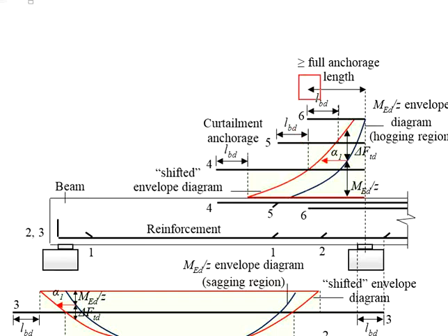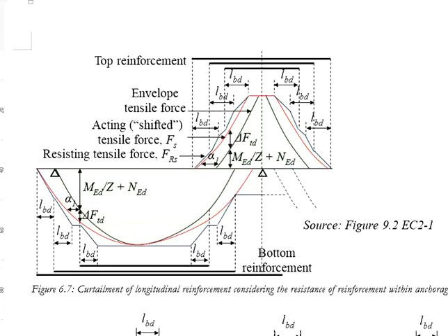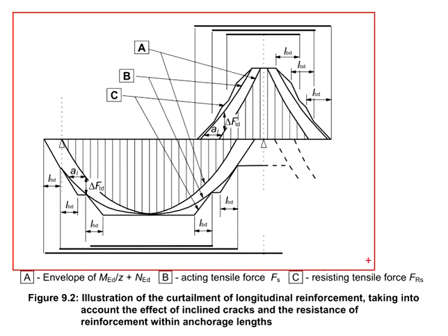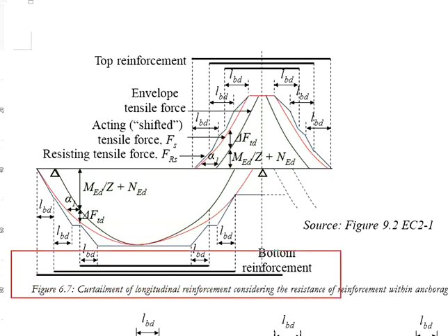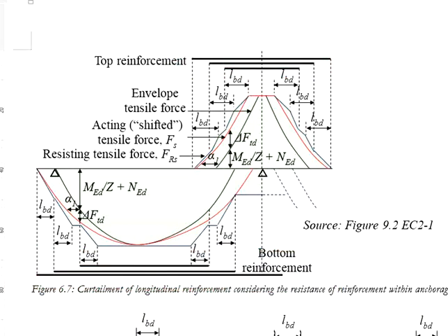There is no overlapping of the lapping length, but sometimes we cannot totally prevent the overlapping of the lapping length, making the actual resistance profile more difficult to predict. Since this is the diagram given in the Eurocode, and we use the Eurocode as our ultimate reference, it is necessary for us to understand the principles governed by the Eurocode. You see here, there are 3 groups of reinforcement, both at the bottom and also the top reinforcement.